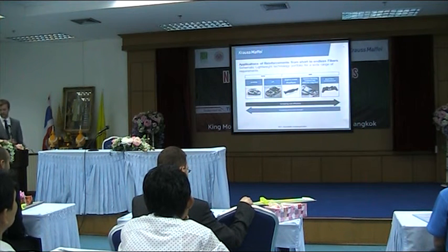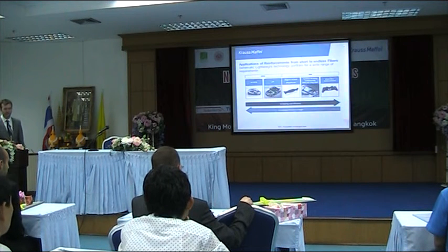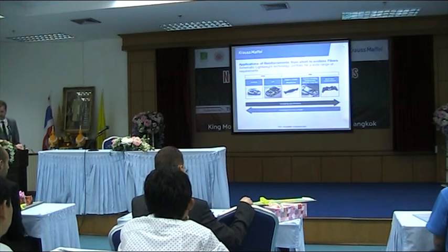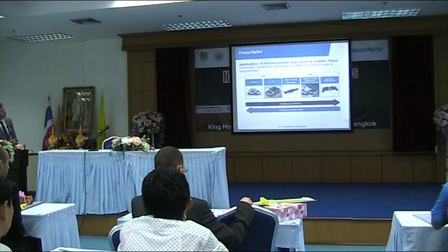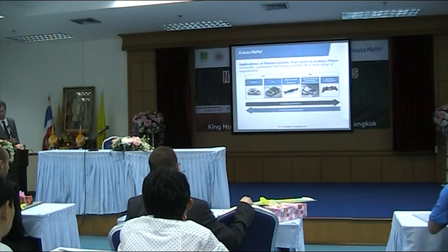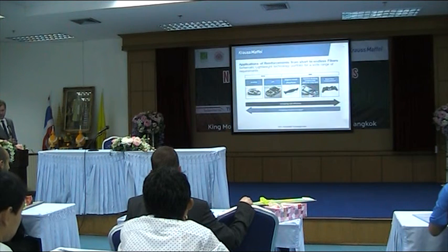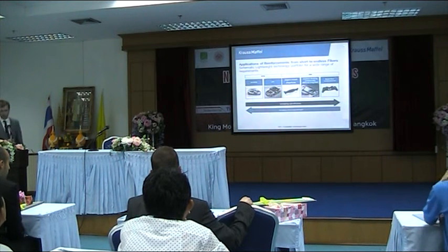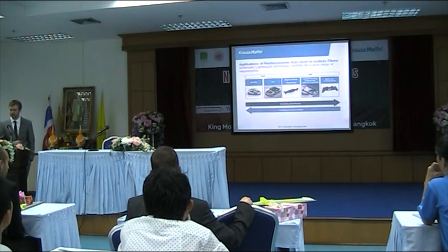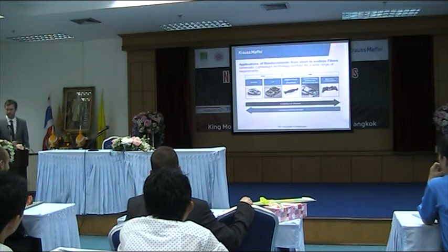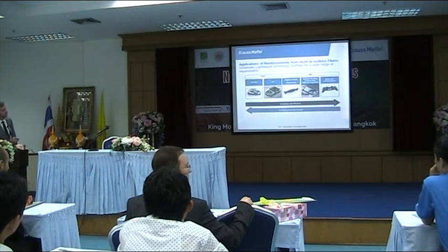produce. And if we combine technologies, this is injection molding technology still, but it's combined with extrusion technology. This is the IMC, the injection molding compounder for long fibers we saw earlier. And now you go from short fibers to long fibers to endless fibers, and now the fibers get even longer: long fiber injection, and also high pressure resin transfer molding. So it's the longest fibers, and of course the high strength.